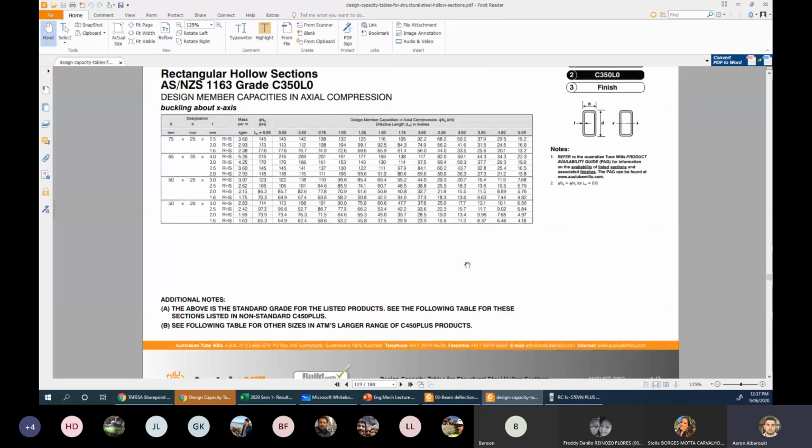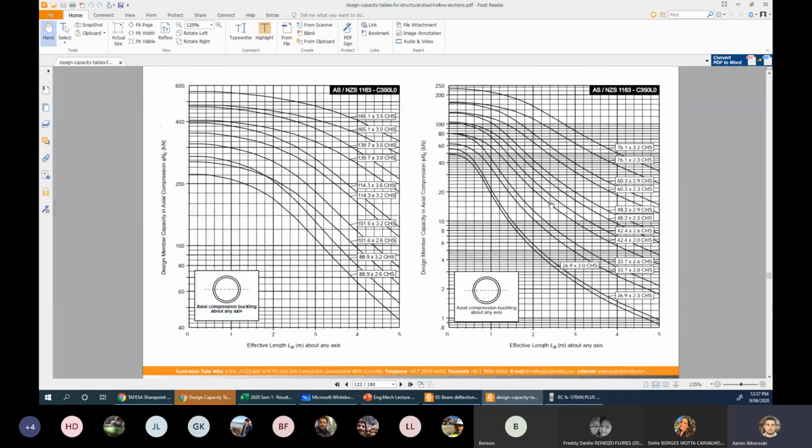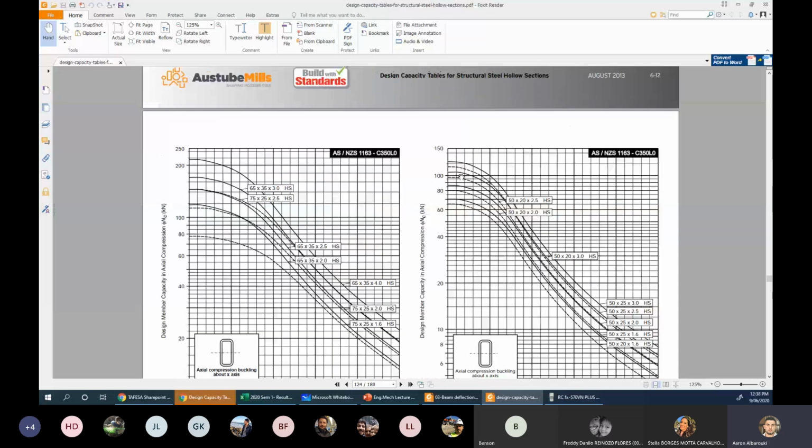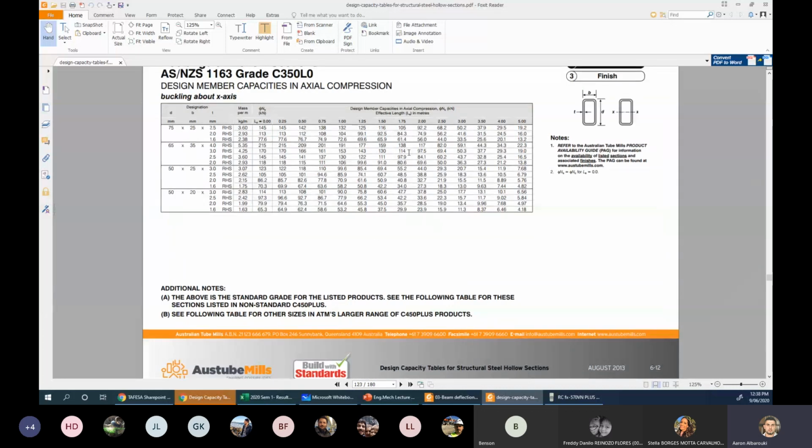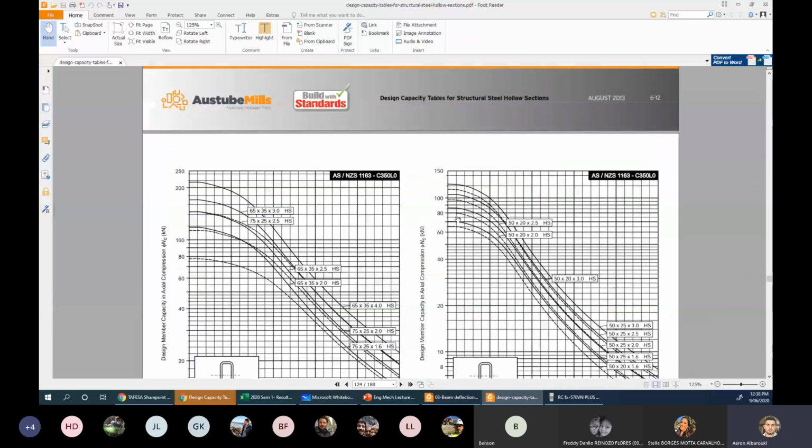And that's for different columns too. In this area, you can say it's linear, a very small area. Outside this area, we start getting curves. That's where Euler's equations stop applying. Next semester, you will learn accurately how we use these tables, rather than these graphs, to calculate our column capacity.